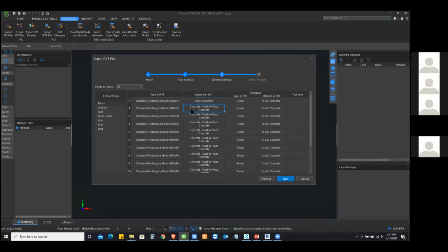So inside of Revit, obviously you either have brick common, or you have concrete, cast in place concrete, and different other information. But these details, again, inside of Revit, you can go ahead with all of them, because that comes in within that. You have different categories, you find out different classifications from there, you can generate all of this information. But here itself, because of the quantification, we don't necessarily go ahead with a lot of details. The material category is, for the most part, to get a classified quantity, so we can segregate it based on the material.